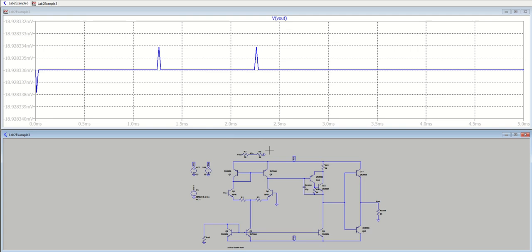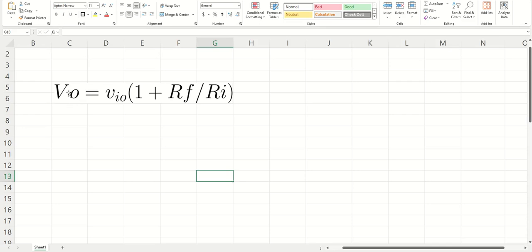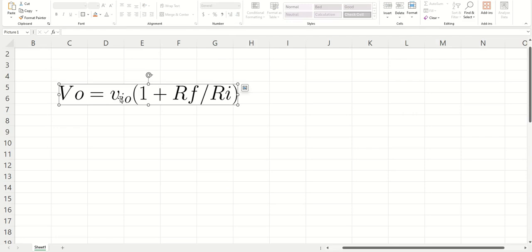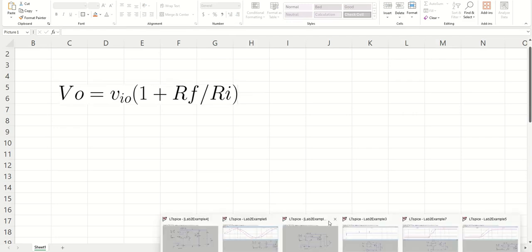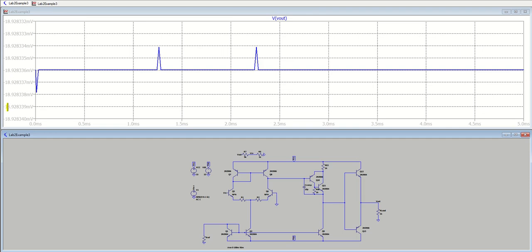And then when you get the DC value, make sure you're considering the gain, because the input voltage is going to be this value divided by the gain. And to see the formula for that, this is the 18 millivolts, this is our gain, this is our voltage offset at the input that we're trying to solve for. So for my example, it would be approximately 1.89 millivolts.